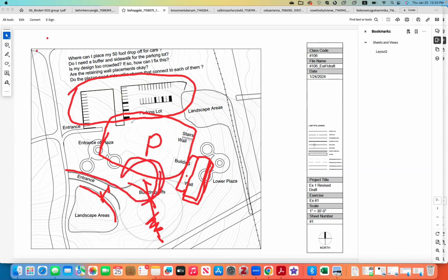And then everything needs to start with the parking lot design. You can do single loaded, 20 parking spaces per row, 2 rows of parking, adding a drop off roundabout at the end. That's the simplest form. And then if you don't have enough distance, you curve it, like Amelia just did.